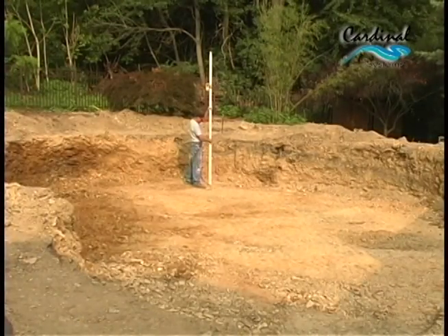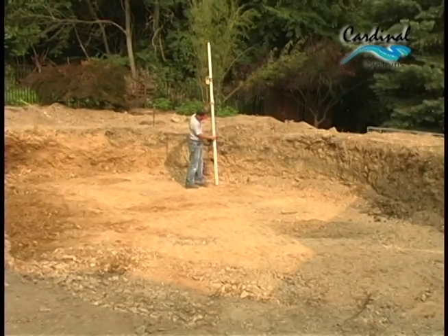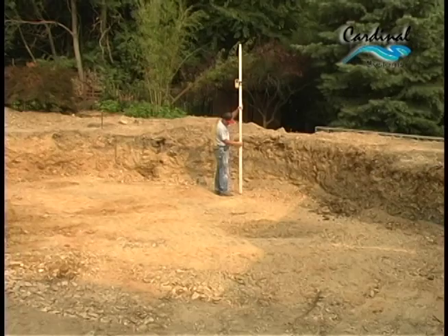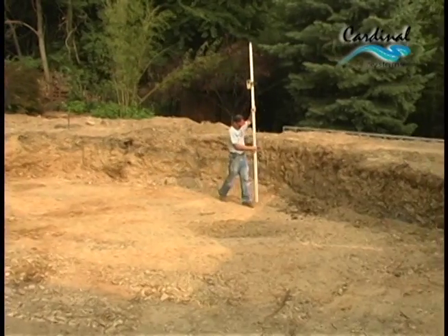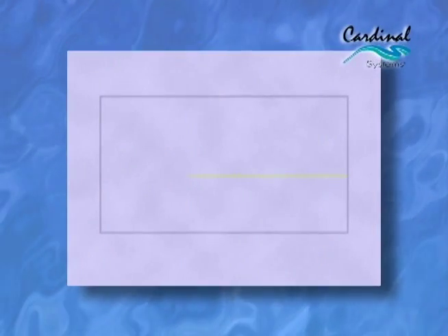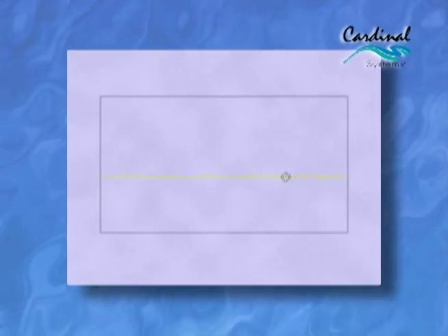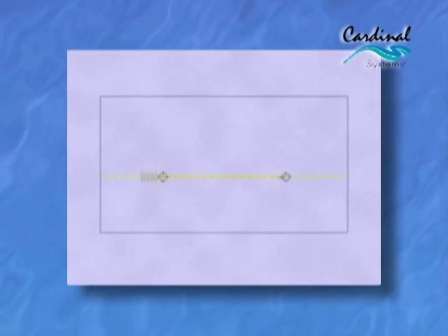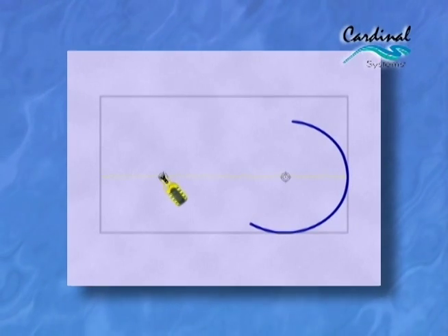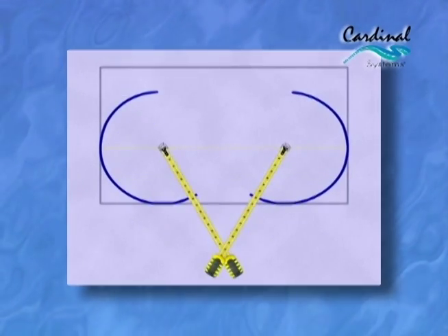Once the first depth has been excavated, double check to make certain your bottom is level and that you're no deeper than maximum established depth. Confident the first depth is accurate, you must now repeat the pool layout as accomplished earlier. To do so, restring your center line and redrive rebar at the appropriate points, and reswing your radii, and spray your layout arcs.